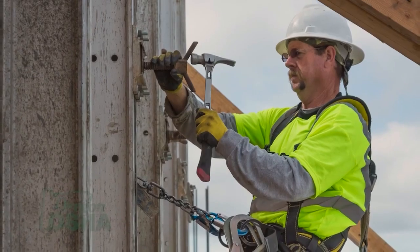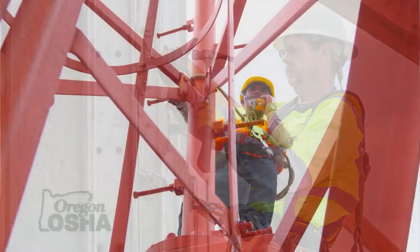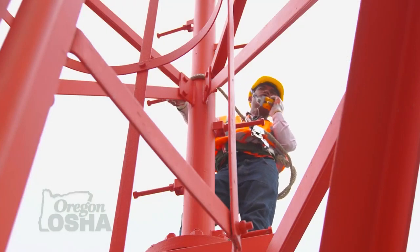You'll see positioning done quite a bit in construction with our form workers, concrete workers, iron workers in construction, people who are climbing towers, either in the wind or telecommunication industry. They use a lot of positioning devices. Also in the electrical utility industry, we use a lot of positioning. A lot of times when linemen are climbing and they finally reach their destination, they can use one of their positioning lanyards to go around the pole as long as it is connected in such a way that it limits them to a maximum of 2 feet of free fall.